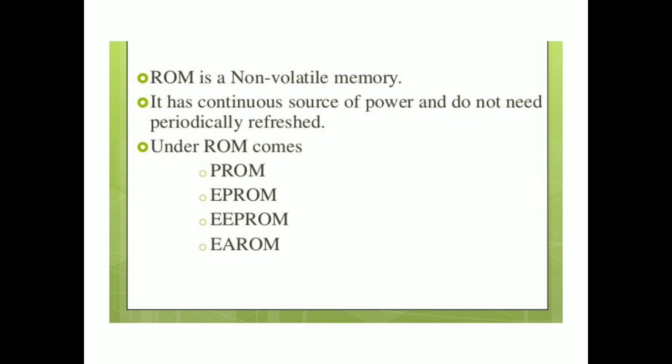So there are many kinds of ROM. The first one that I'll be telling you is the mask programmable ROM, or MPROM. They are custom made for the customer. Their contents are programmed by the manufacturer. Since they are mass produced, they are inexpensive. The customer cannot erase or program it afterwards.